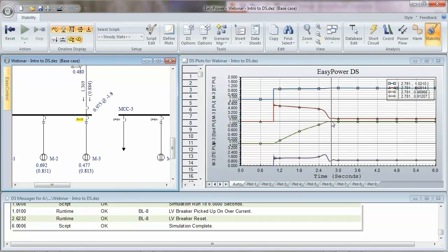So 3 minus 1 is 2 seconds. It took us twice as long to start by doubling the inertia. So that's a key value. You see, those are some key values in that data. But again, we're going to put typical data values in there for you, and we're going to put a typical inertia value. If you want to really get much closer, then you have to start adjusting each of those parameters to get it closer to what your motor actually is.